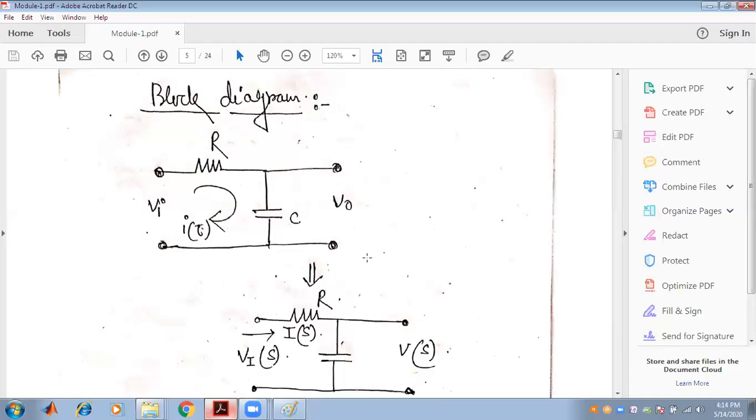If the poles are lying on the right-hand side of the S-plane, the corresponding nature of the system is diverging in nature, and the system is called the unstable system. And if the poles lie on the origin, this is called the marginally stable system, and the corresponding nature is also seen.